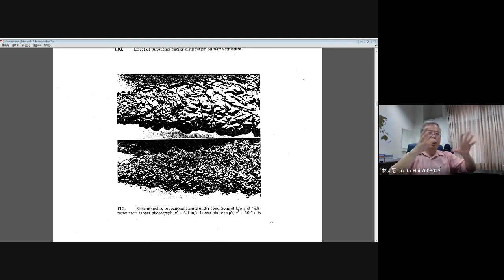They do not have a smooth, small curvature flame surface. And this is a typical comparison to let you know how the flame surface changes with the increase in turbulent intensity from small to large. The flame shape changes from a wrinkled flame to a roughened flame surface.